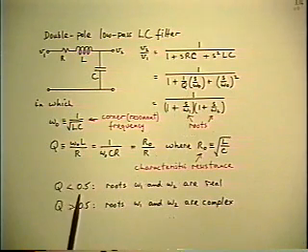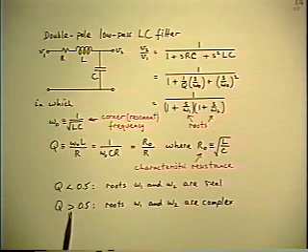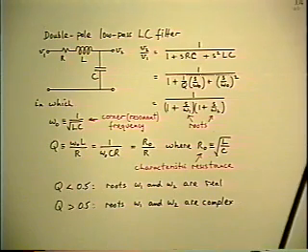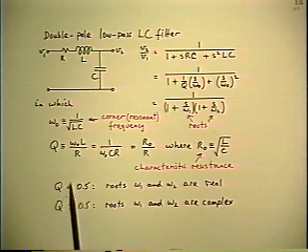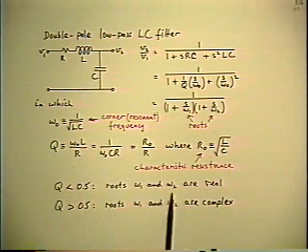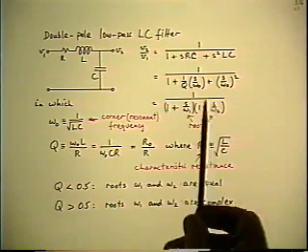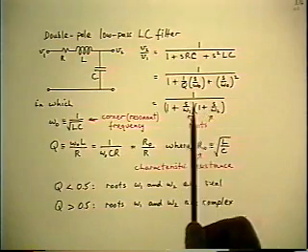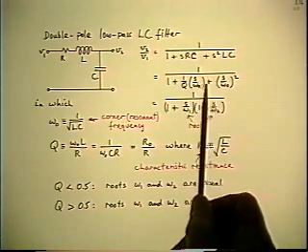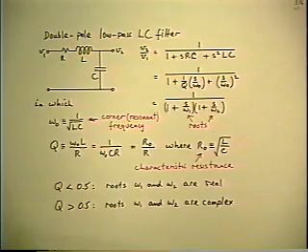And the Q is now the remaining parameter that determines whether you have complex roots or real roots. You knew that already. But now we see the real reason why there is only one parameter that determines the nature of the results. Well, now that we have these two roots, omega 1 and omega 2, let's look at what some typical shapes are for the magnitude and the phase of the quadratic transfer function.